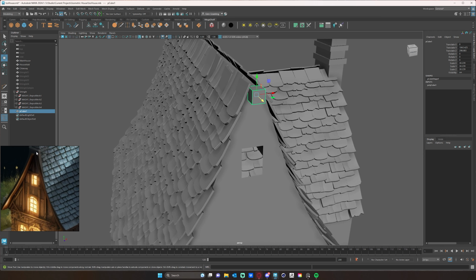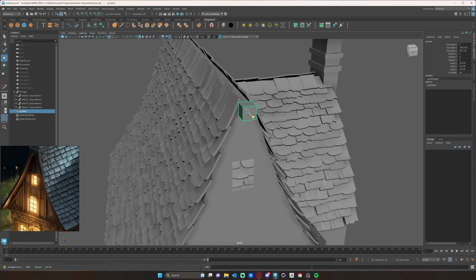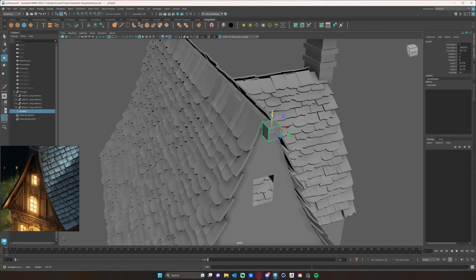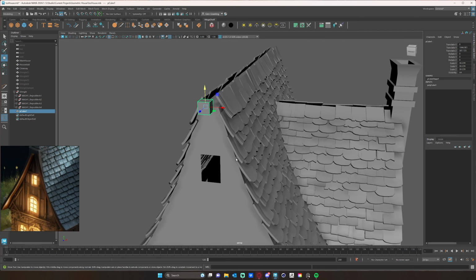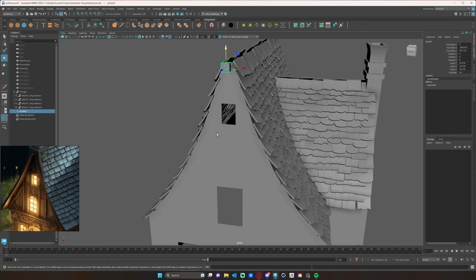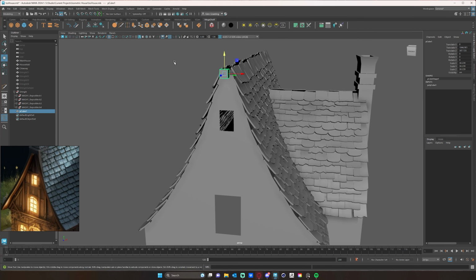And I'm thinking I want to add a little bit of detail here and make a little indentation that goes all the way down to add a little bit of extra detail to this. Since this is something that has symmetry, with two symmetric sides, and I don't want to have to model both sides, in this case I'm going to turn symmetry on. So I'm going to have my object selected here, and come up here where it says symmetry off and turn symmetry on to object X.